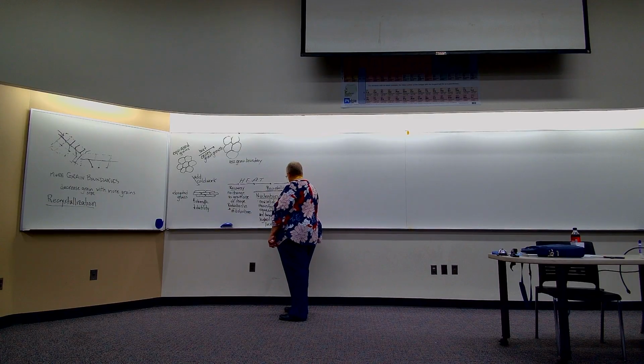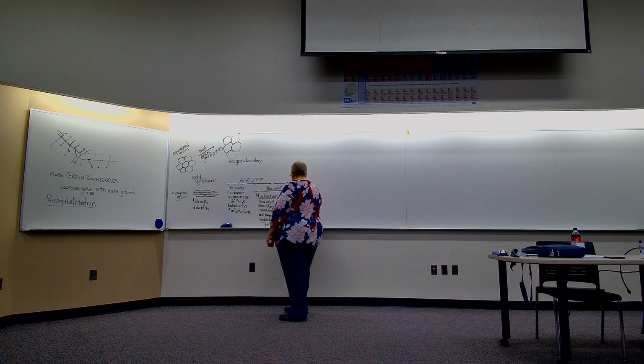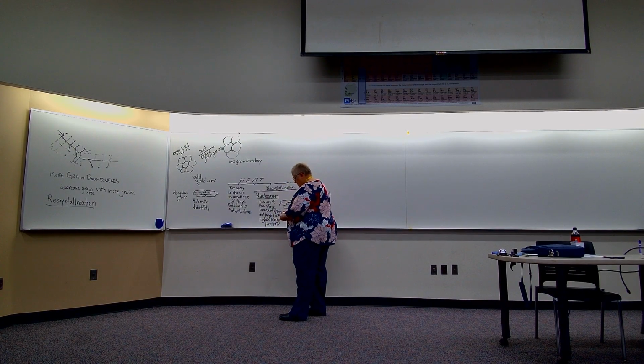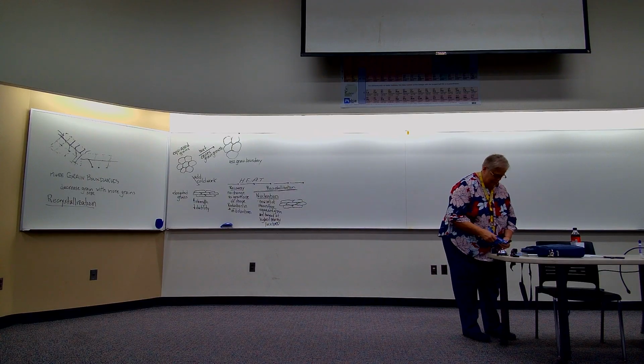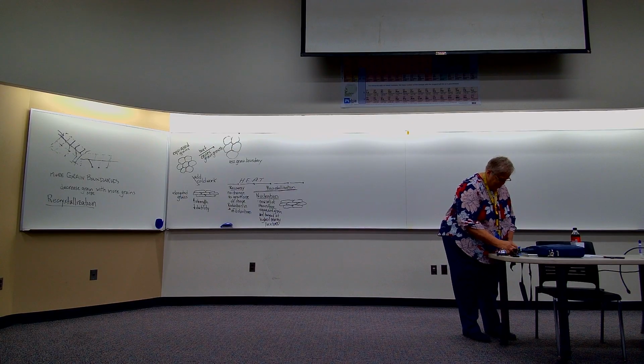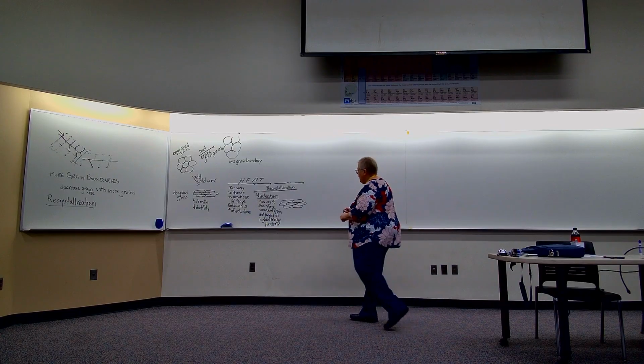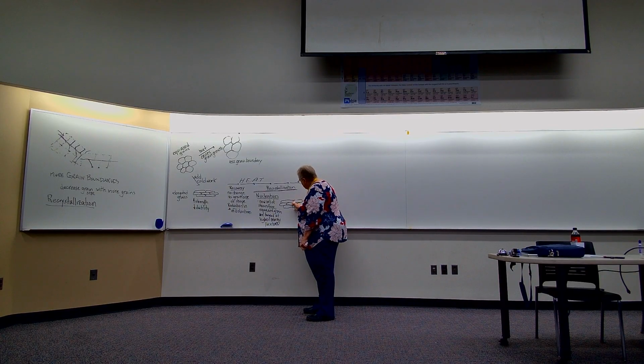So we have these grains, and those grains have these new strain-free grains forming at high energy locations. Highest energy locations are the places where 3 grains are coming together.